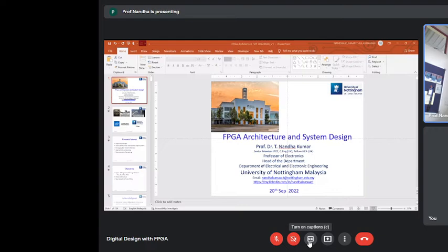But for the time being, I will touch on PLA, PAL, and CPLD. Then I will move into FPGA architecture, a general architecture, which is an SRAM-based architecture. Later, I will show you the other architectures of FPGA as well. The final idea is to introduce some of my topics, which is non-volatile LUTs for FPGAs, my research area. Currently, we have also developed a non-volatile FPGA architecture.